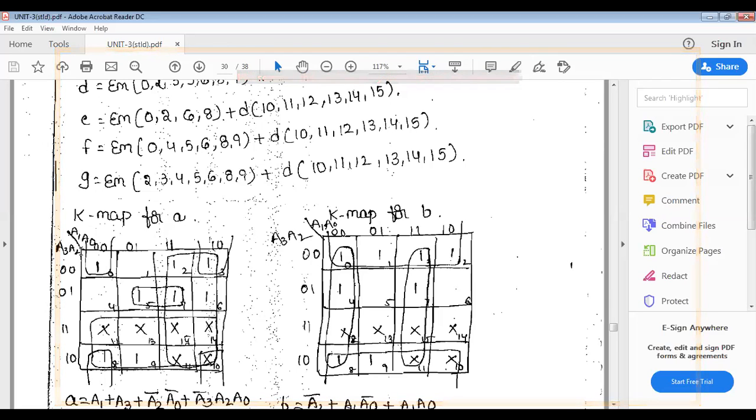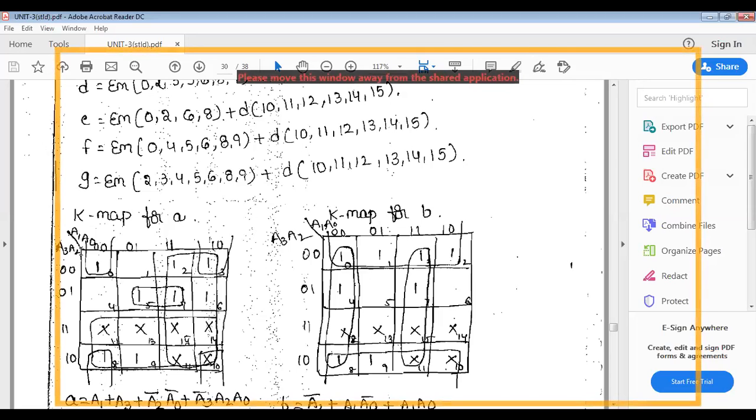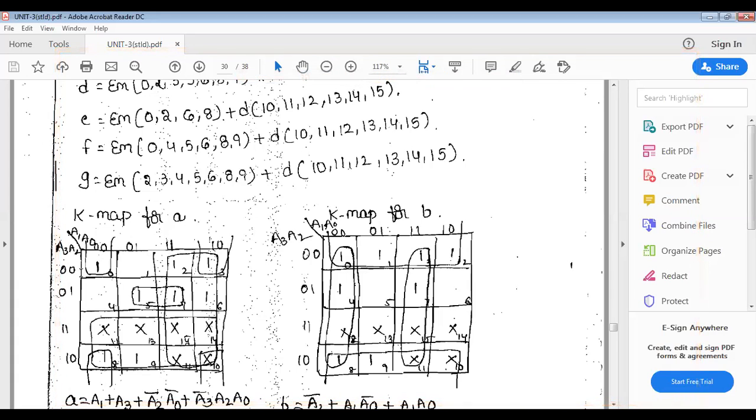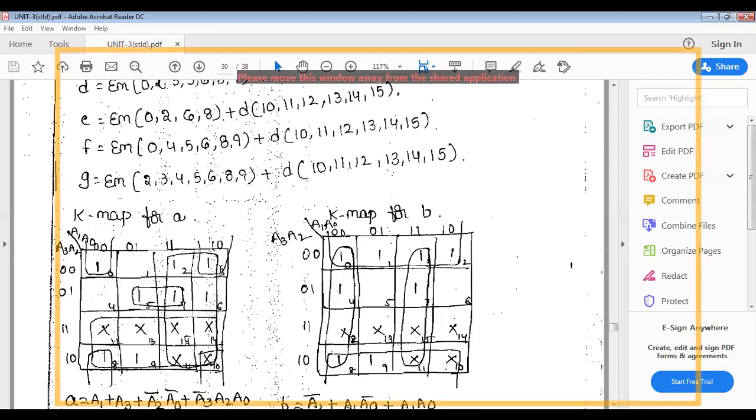So I'm taking LSB bits A0, A1 horizontally, and MSB bits A3 and A2 vertically. 00, 01, 11, and 10 is the Gray code. The Gray code only is used in the K-map to reduce the Boolean expression, to give the minimum number of literals. See, 0000 means it is the 0 box. 0001 is the 1 box, and you can always take the vertical values as MSB bits. 0011 is...